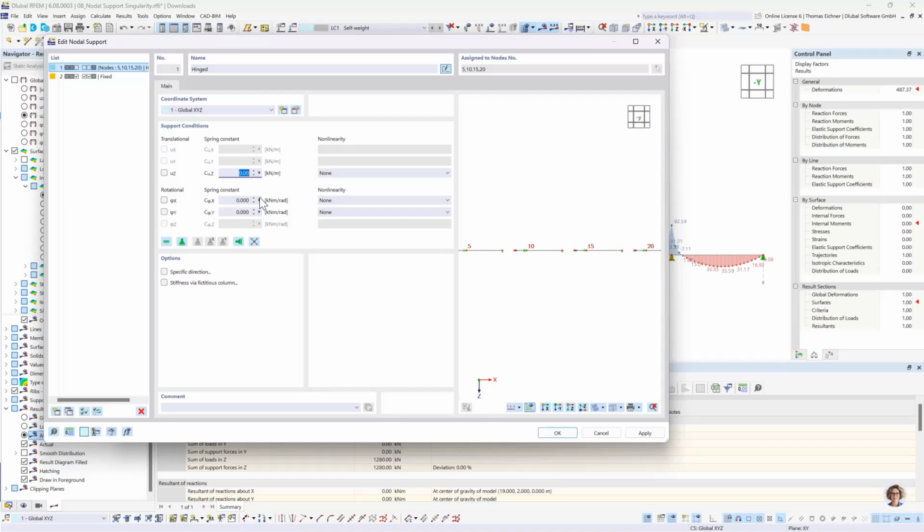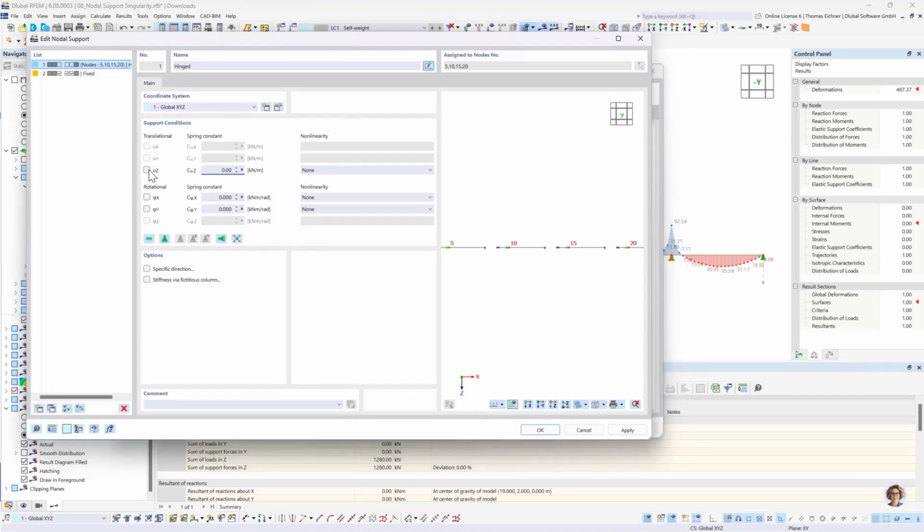And with that said, if we add here some flexibility, well, not flexibility, some deformation capacity of the support, it would be able to deform like in that direction. But it would have to take the force anyway, because the force can't go anywhere else. That's only possible with statically overdetermined systems. That's the reason why it wouldn't help in this case.